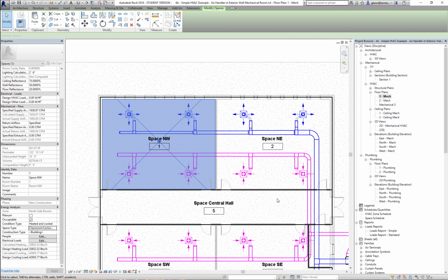What we tend to do is we take our spaces and we aggregate them into zones. And zones are all about, well, if these two rooms want to have basically the same thermostat or control system, so if heating and cooling turns on in these two rooms, it's only in these two rooms and not those two rooms, we'll make that a zone independent. If there's one zone for the entire building, then if the air is blowing anywhere in the building, it's blowing throughout the building. So zoning gives you a little bit finer control. So we can put thermostats in the different rooms.